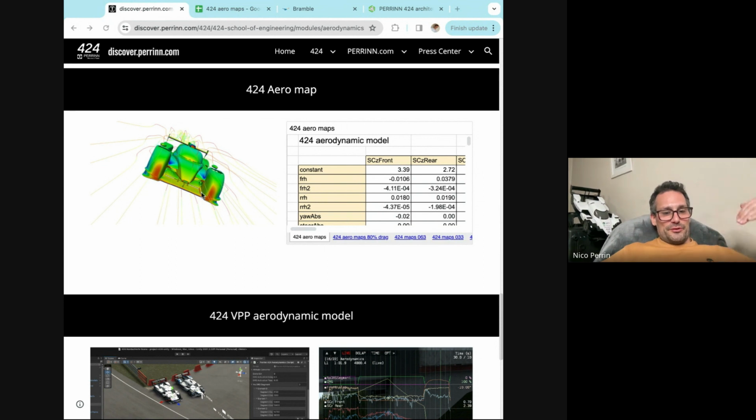When you do the same under the car, it's different because the ground effect is helping you. When you have to go around geometry aggressively under the car, the ground is actually helping you do that, because the proximity of the ground helps the flow go where it needs to go. On the top body, it's not true. And I made a mistake there. Apart from that, honestly, the rest was very sound.